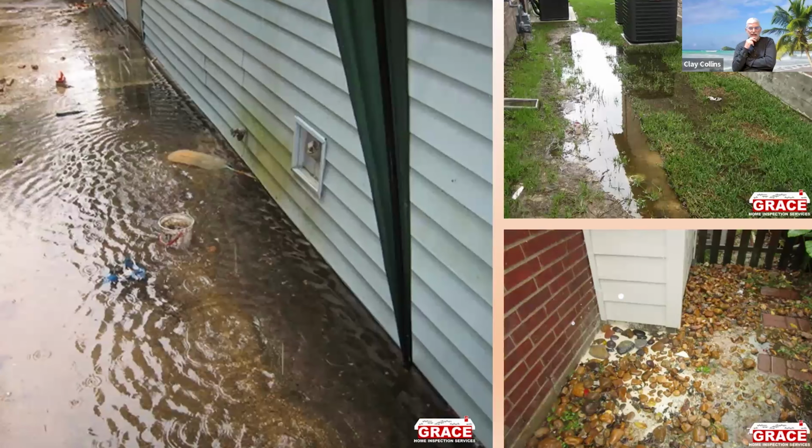You can see the drain clean out on the left by the hose bib. That's vinyl siding. It's sand. It's not even sodded. I don't recall the reason that it was sand and not sod, but because it's vinyl, I know that this is not a new home. You have terrible impact of water on the house. And if you look at the green algae buildup, I don't believe that was because of secondary condensate drainage. But this is a real problem.